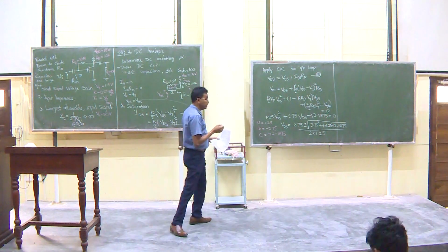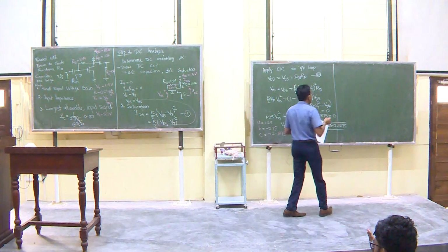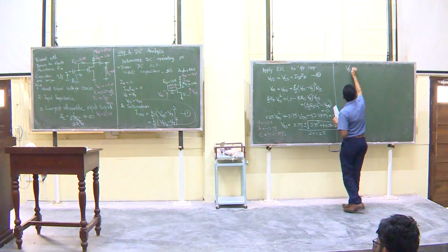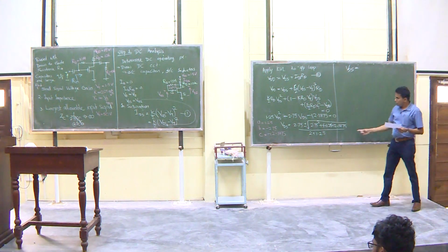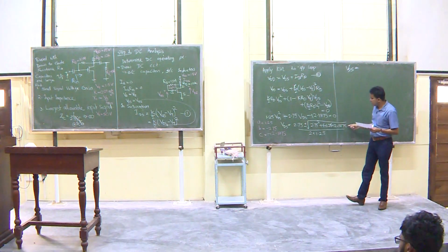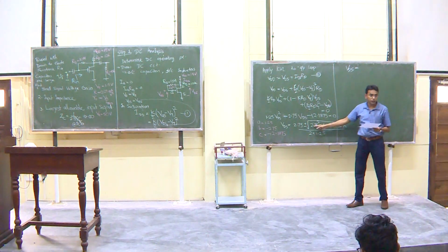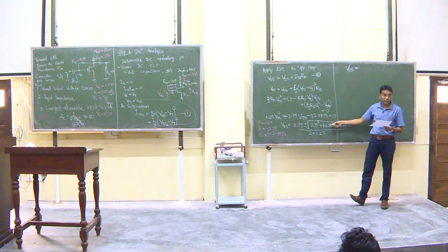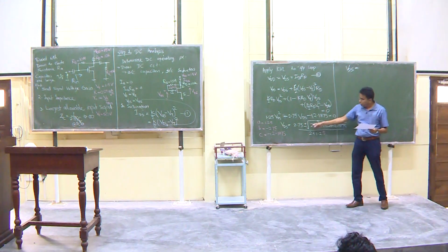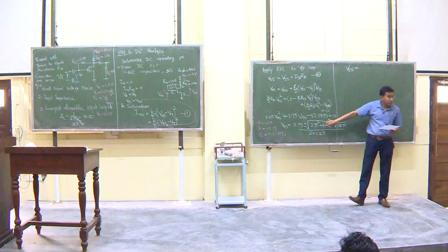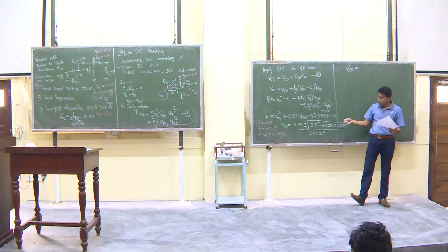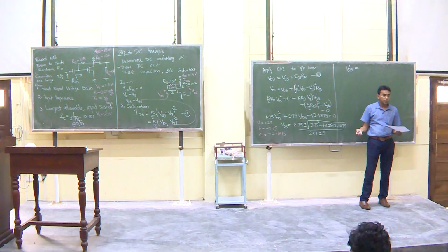So, for VDS, you put the values in and see, obviously what is inside the square root is bigger than 2.75, so 2.75 plus something is there, right. Therefore, if you take the negative sign here, 2.75 minus something bigger than 2.75 will become negative, right.